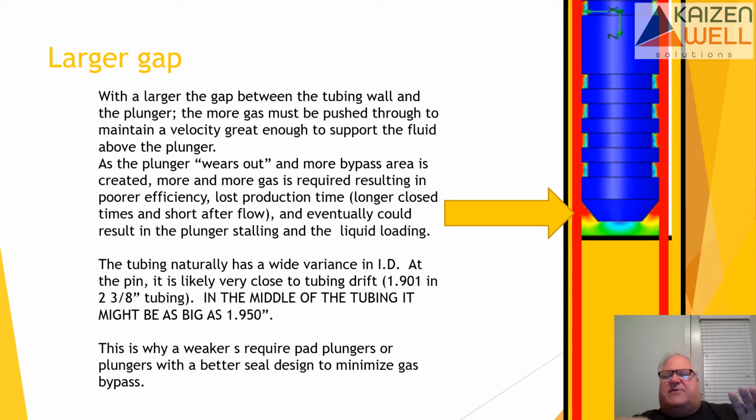And what's interesting, other than maybe the first or second plunger you replace, you'll start seeing that those plungers wear at a very consistent rate typically. So if it wore out in 3 months in this well before, it's going to wear out in 3 months the next time. And they pretty well stay like that. I mean, over many, many years, you might start to see it extend because it's going to just rub all the little rough edges off the tubing. But generally, you can take it to the bank.